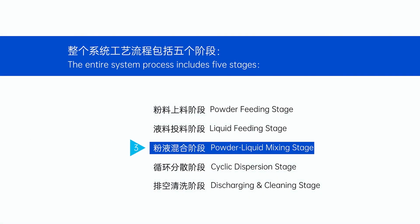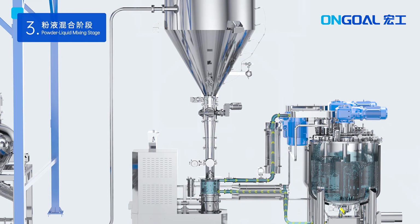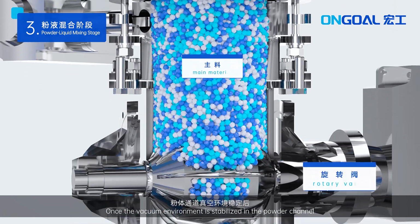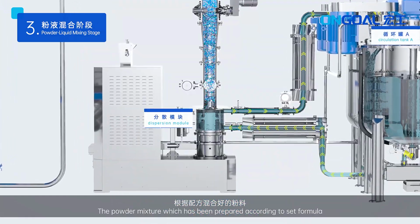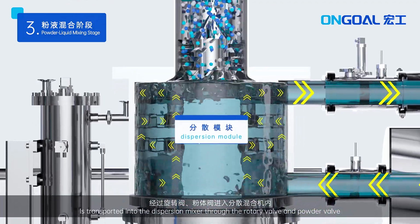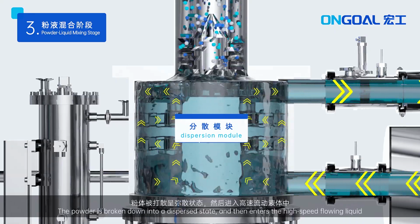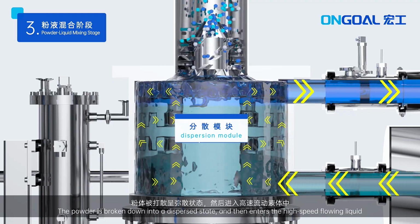Powder-liquid mixing. Once the vacuum environment is stabilized in the powder channel, the powder mixture, which has been prepared according to the set formula, is transported into the slurry mixing module through the rotary valve and powder valve. The powder is broken down into a dispersed state and then enters the high-speed flowing liquid.